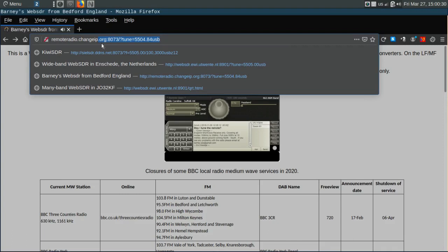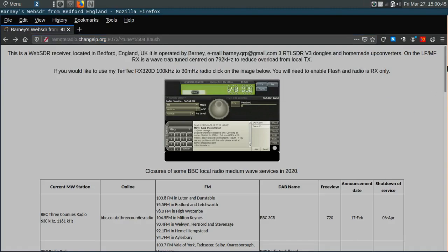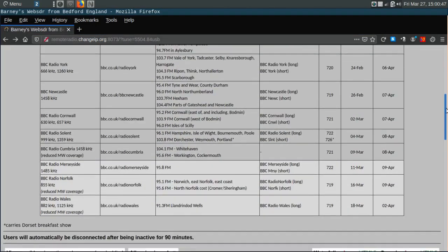That's how I tuned in the signal with minimal error. He's using an RTL SDR, I believe, and it's off in frequency by about 160 hertz, so I have to compensate for the offset by moving this thing down about 160 hertz.